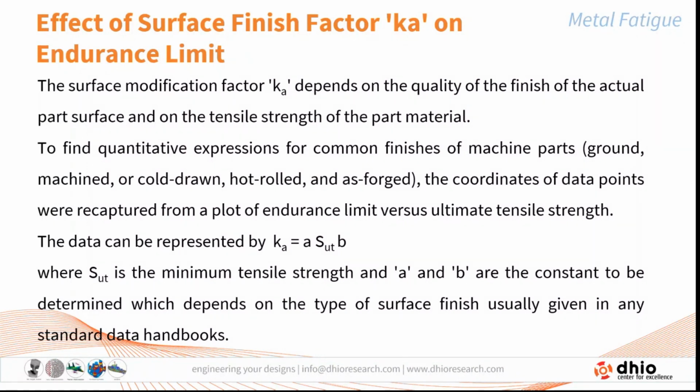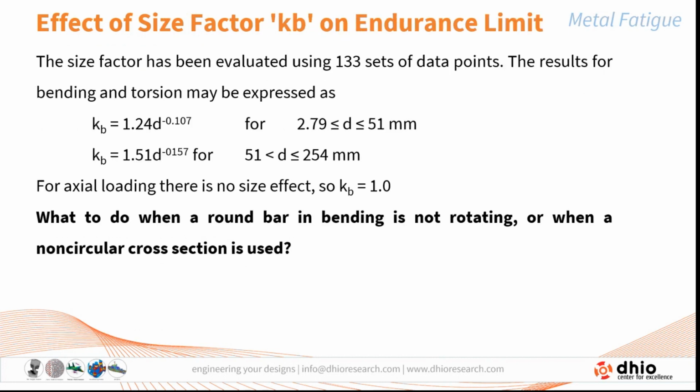And the data are being represented by Ka equal to A into Su to the power B, where Su is the minimum tensile strength, and A and B are the constants to be determined, which depend on the type of surface finish, usually given in the standard data handbook.